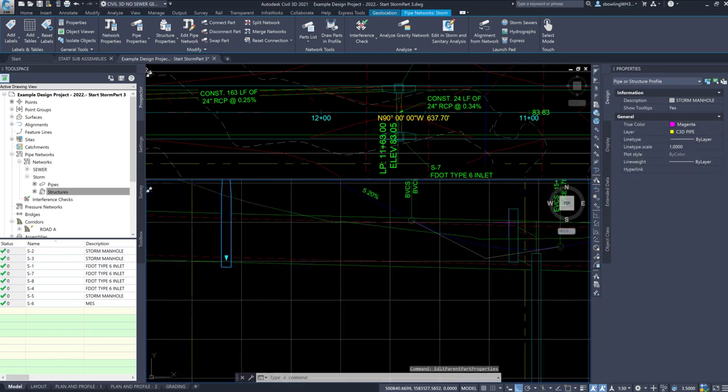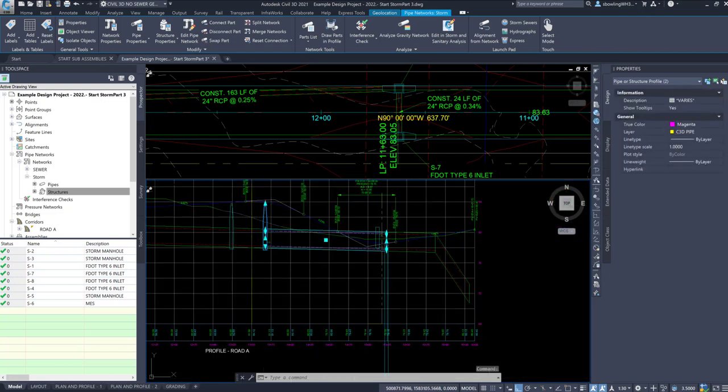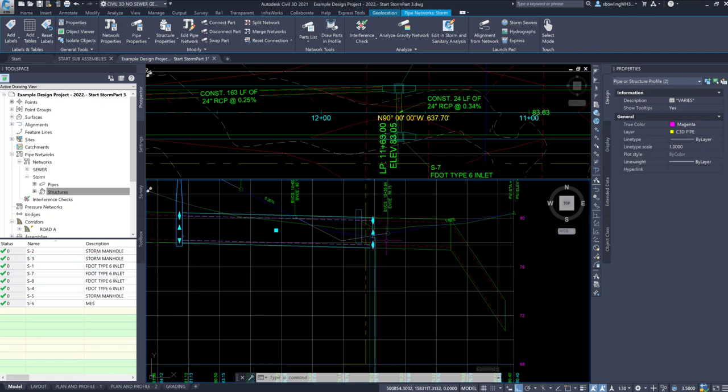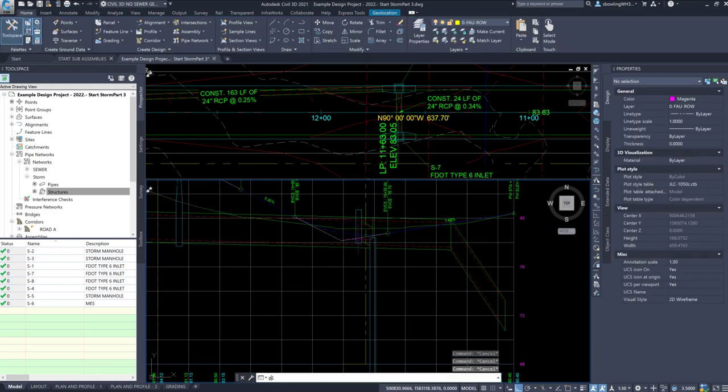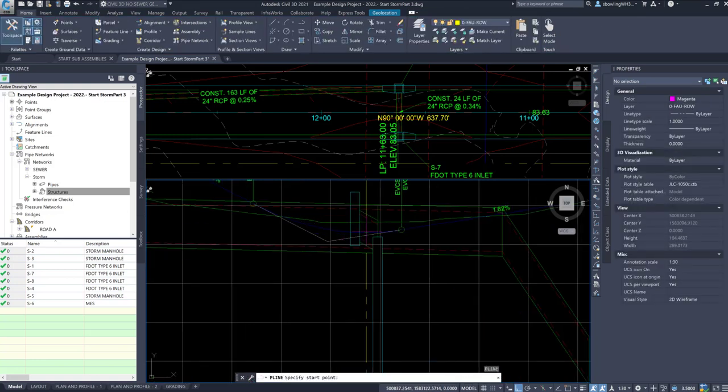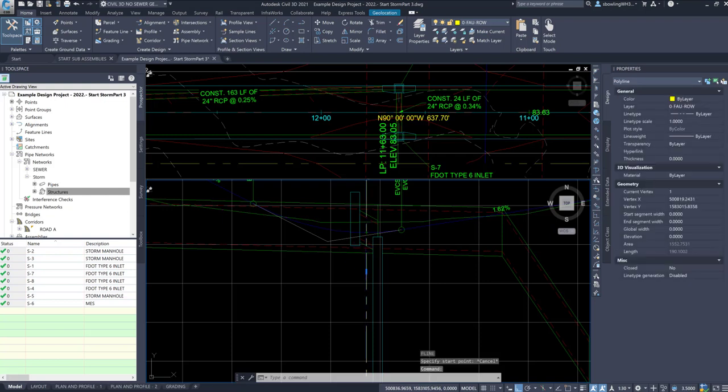All right, now this is where it goes wonky. So I am way not working here. You can only do this if you're actually in a drawing that has the pipes in it. So I can see that I'm way above the ground. We know that from the grade, and I'm just going to draw a line from where that low point is. I'm going to delete this line.